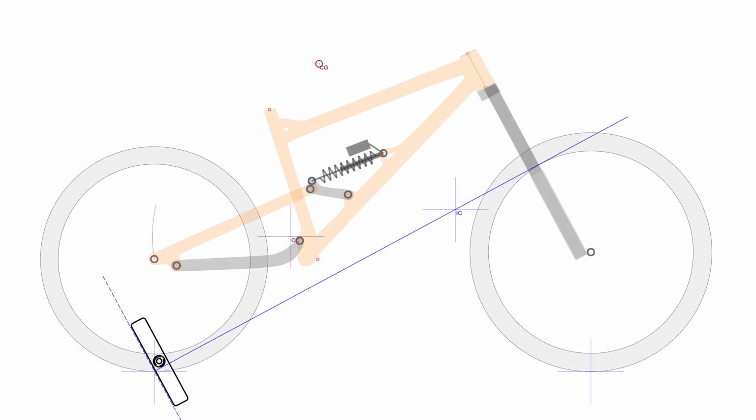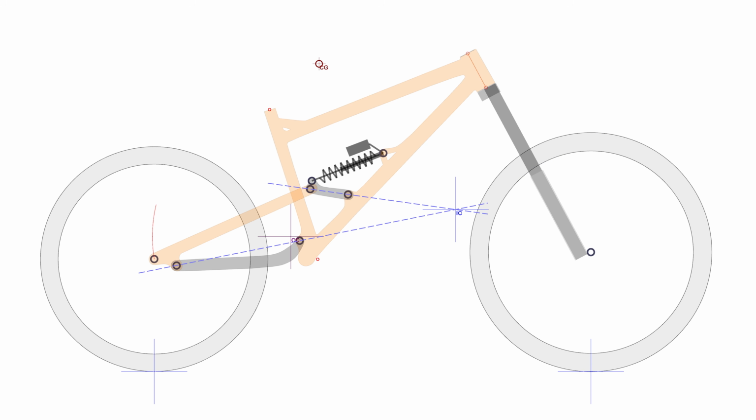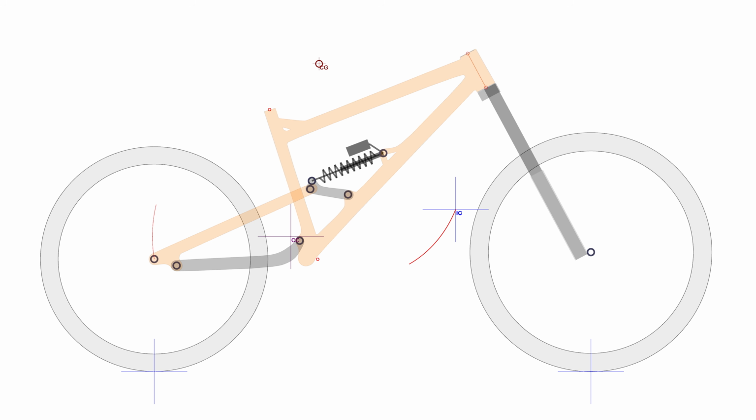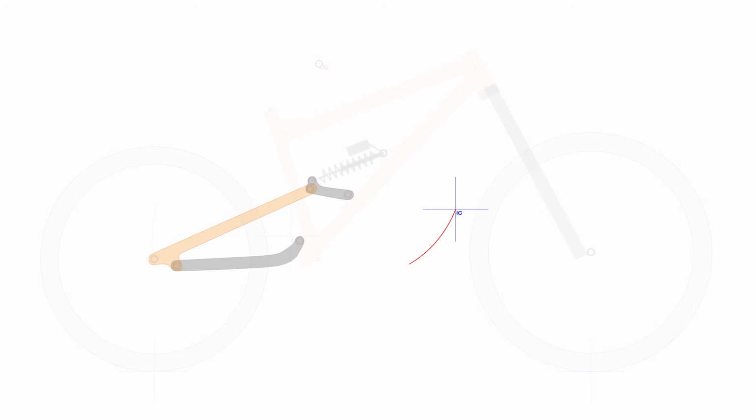As mentioned before, the driving or braking force in the suspension is felt at the contact patch, which is also where our slot is located. This slot is perpendicular to the so-called instant center. On a 4-bar linkage, the instant center can be found at the intersection of two lines through the rocker and chainstay pivots. This point is called the rotational center because you can imagine every point on parts that are not fixed to the main frame rotating around the IC when the suspension moves. Or at least momentarily. On most linkages, the IC changes its location throughout the travel. That's why instead of a simple rotating motion like on single pivots, the suspension movement on some bikes is a little more complex.